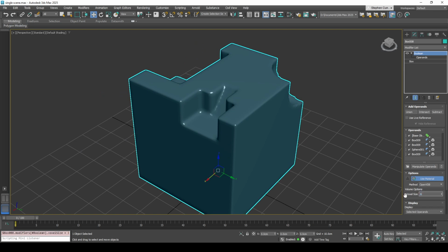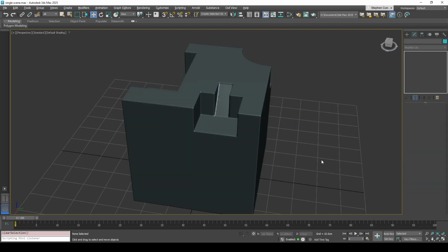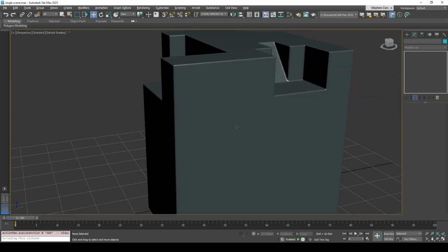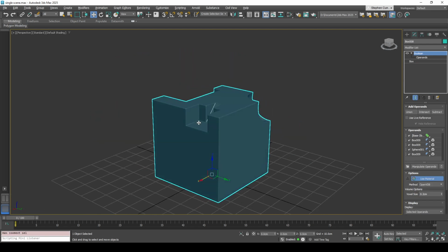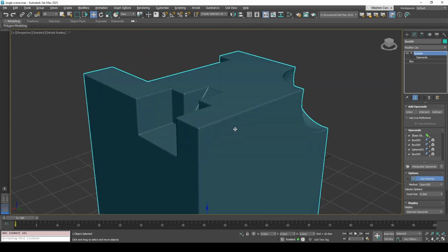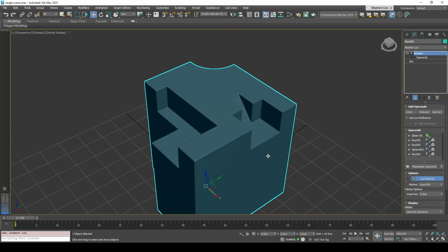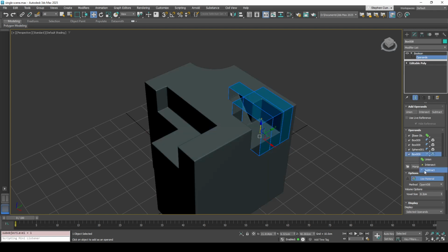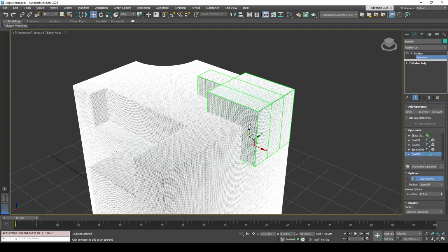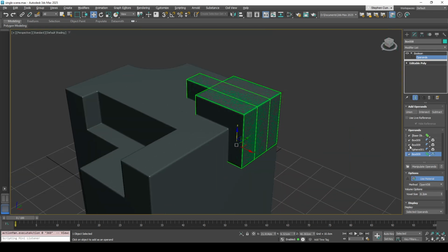So we'll have a look at the sharpness of the cut here, so you can see that's quite dense, but it's not done a bad job there of connecting those areas up and tweaking that through the instance itself. Any of these you can go back and edit. So you can change this, put it as a union, and it'll attempt to unify this.